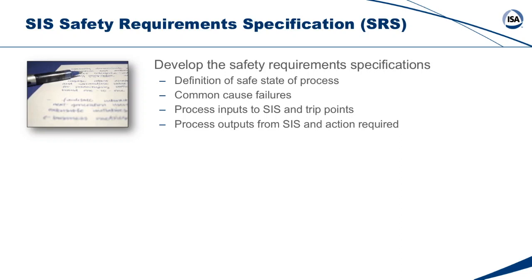What are all the outputs? What are valves, pumps, motors? What goes on? What goes off? What energizes? What de-energizes? What functional logic, timers, latches and resets, and how will bypasses be done? You have triplicated transmitters. How will you do discrepancy alarms? And how will bypassing one affect the logic of the others? Response time. Do you actually have 36-inch valves that have to close in half a second?